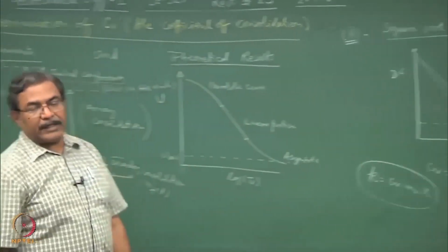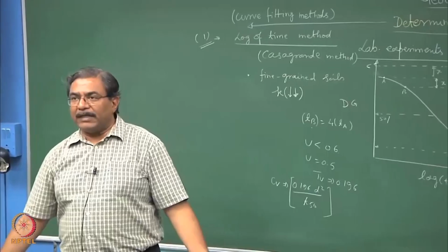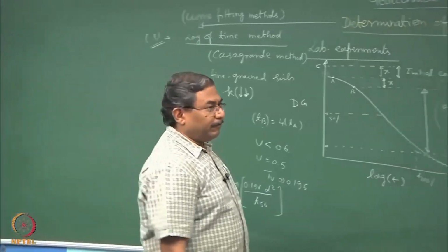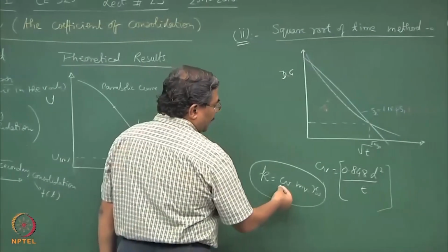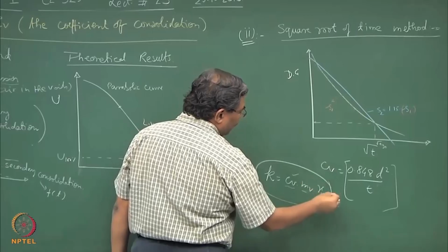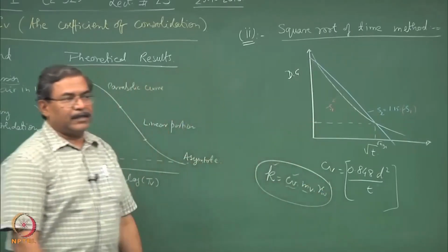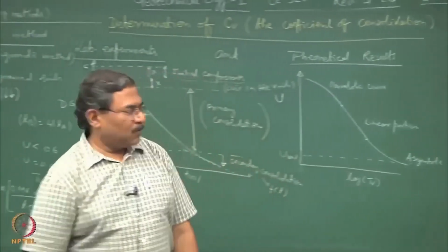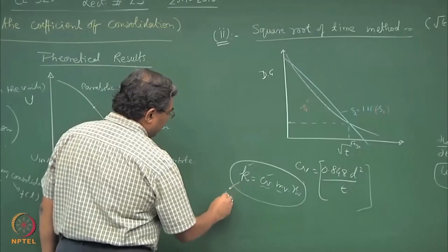Now, this hydraulic conductivity is going to be much precise and better in the way, because it is a controlled experiment, and hence if I know the CV, if I know the MV, gamma W is known, I can obtain the hydraulic conductivity in a better manner. So, this way I will be getting a better and precise value of K.